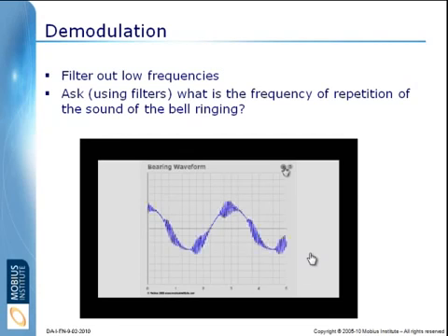And then we can ask, using filters, what is the rate of repetition, or the frequency, of the sound of the bearing ringing? So again, when I hit it once, it makes a sound. And with filters I can ask, how frequently is that high frequency sound occurring? Bing, bing, bing, bing, bing.